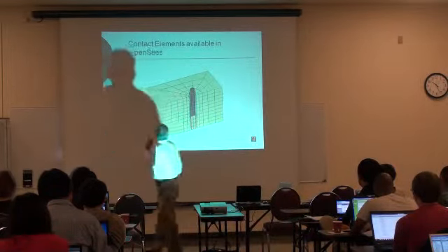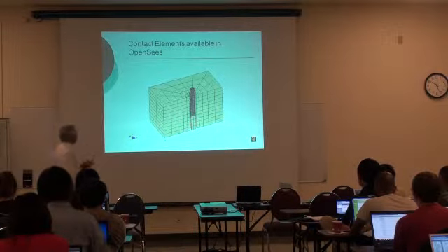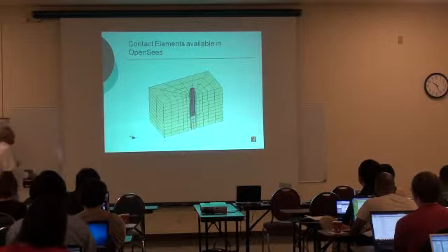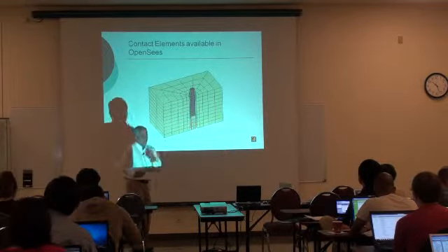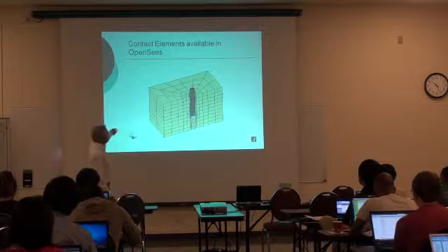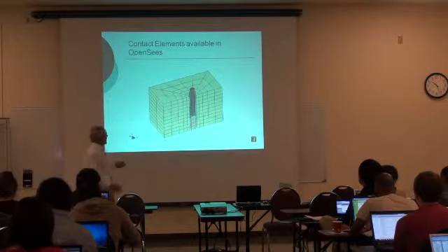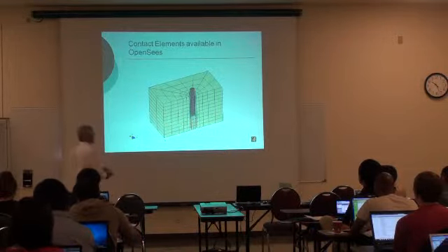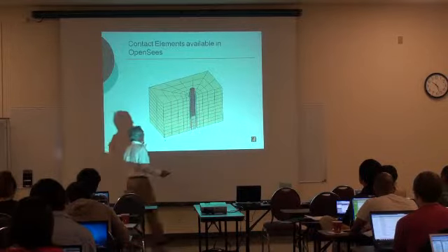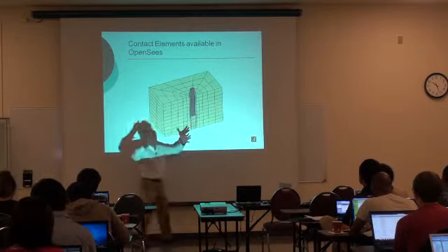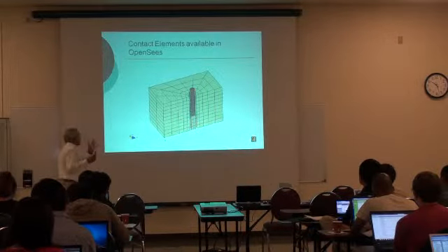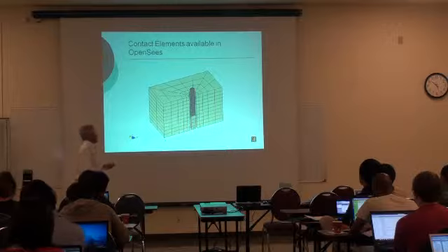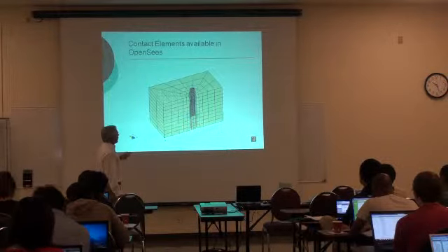Finally, how to model a pile if you're doing a 3D analysis? You can't connect the pile with just one spring. I would need an infinite number of springs here, and then I would have a problem because those springs, the PY springs, TZ springs, represent the whole pile. So how do I put many springs, each one representing a portion of the pile? That's a problem. So one alternative is to say, well, I want to model the pile in this way.